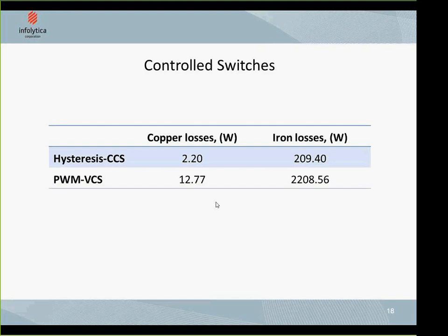The other advantage of using MagNet, and of determining the location of the averaging windows, is that I can do transient analysis and also evaluate my fault analysis. Because we know that switching transitions are going to affect the transient performance of your devices, you'll be able to better represent your device performance and see whether it's meeting the design criteria that you set out.